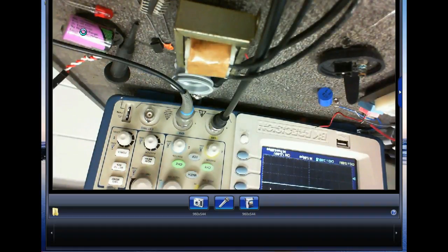because those transistors are either on or they're off. When they're on, they're dropping very little voltage, even though current flows through them and it does get warm. But when they're off, they're not doing anything. In a linear power supply, your regulator always has to drop the difference between the unregulated and the regulated voltage. So in those power supplies, the transistors are going to be bigger.